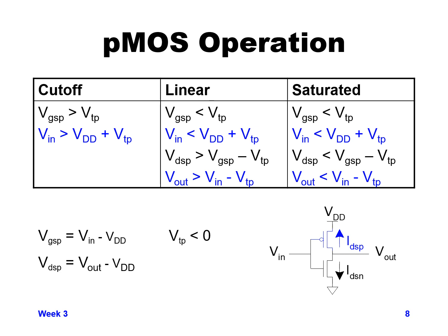One thing to keep in mind is the threshold voltage for a PMOS, instead of being a positive value, is a negative value. So again, the equations get flipped in terms of greater than and less than relative to each other, because you need to be less than VDD instead of greater than ground for an NMOS device. So for cutoff region, our Vn has to be greater than VDD plus VTP. Keep in mind, V threshold for a PMOS device is a negative value, so as long as Vn is higher